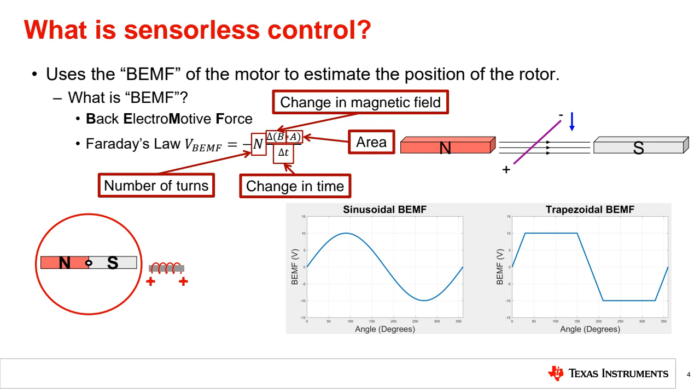If you learn how a generator works, you can check this. For example, if you use a drill machine, you can couple the drill to your motor shaft and rotate it at 3000 RPM, and you will see your motor generate back EMF at the end of the winding. This is the winding's induced voltage.